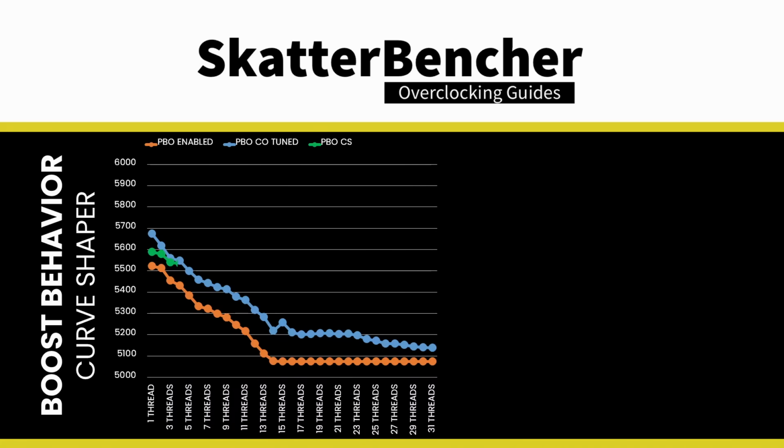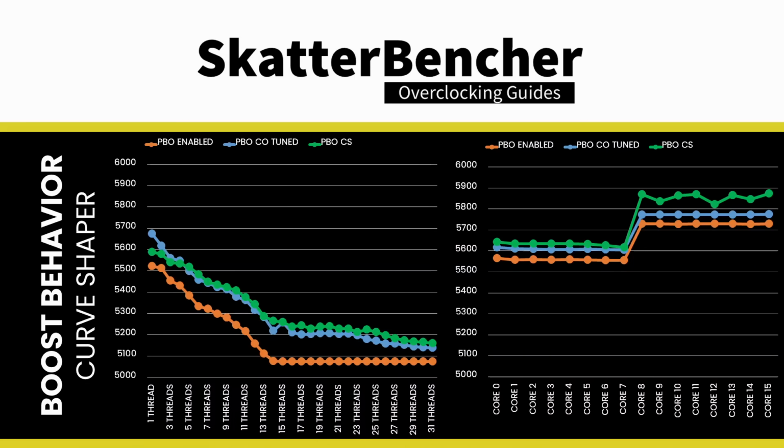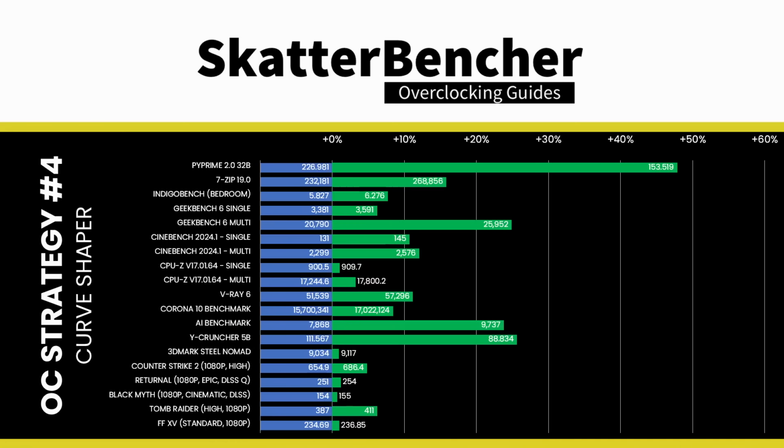the boost frequency at one active thread is about 5,588 MHz, and the average boost frequency gradually trails off to 5,160 MHz when all cores are active. In light, single-threaded workloads, all cores in CCD0 can boost to over 5,630 MHz, and all cores in CCD1 boost to over 5.8 GHz. We reran the benchmarks and checked the performance increase compared to the default operation.